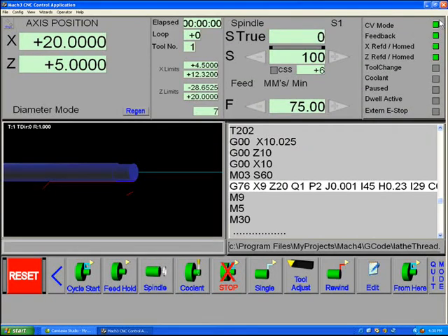We have indicator lights to show us if we're in constant velocity mode, something you normally are in turn, and whether or not feedback is enabled in the software. Feedback being enabled tells us that the software will be looking for a spindle index pulse, and will be using this spindle speed to control various things in the program, such as threading, synchronization, as well as constant surface speed. This DRO down here is the constant surface speed.